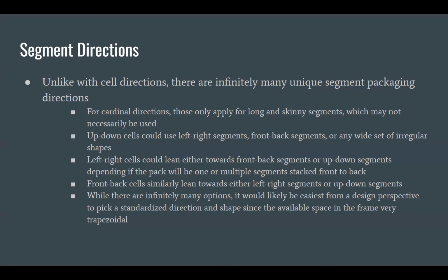Also, a more serious issue with putting multiple segments in parallel is that if they're not exactly the same amount of charge when you connect them to each other, you get extremely high currents as they instantly equalize the charge level, and if they're far enough apart, that can be really dangerous. And then in use, they're not going to discharge exactly the same, as you have some balancing issues, and it can be dealt with.